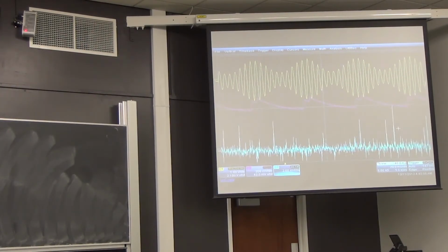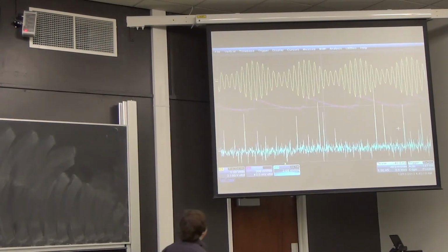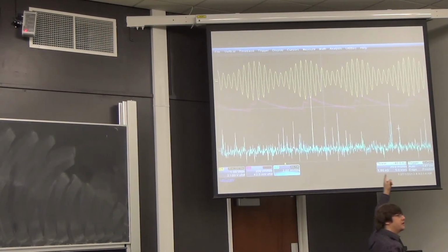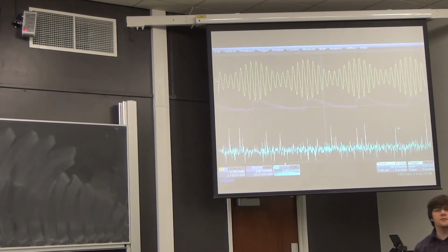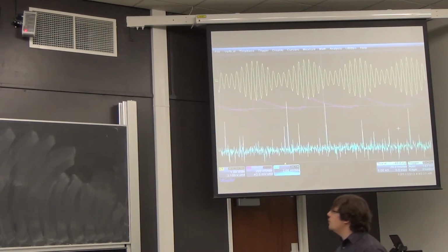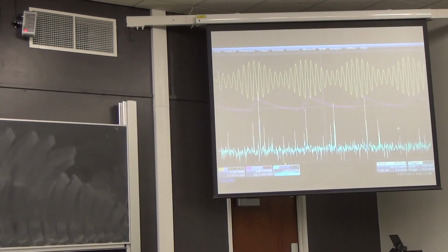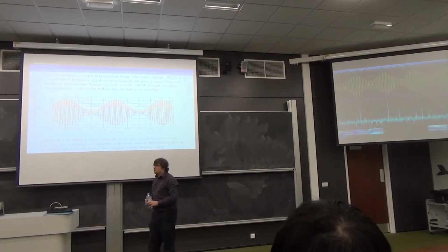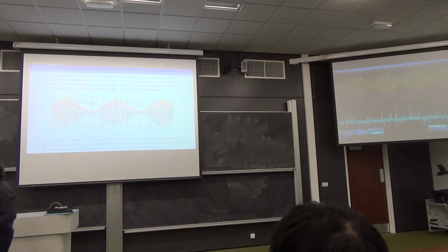So anyway, this is a couple of 100 kiloohms. We can see that it's very much like the blue line on the main screen. We've followed it across the top of the peak, where the capacitor really needs to gain a lot of charge. But the capacitor has no mechanism of losing charge because the resistor is very, very big. Time constant far too long. So it doesn't follow the waveform in the region where it's decreasing on a per cycle basis, sort of 0.3 milliseconds through 0.4 milliseconds. So this would not give you a faithful representation of your original signal when you demodulate it. Where are we now?